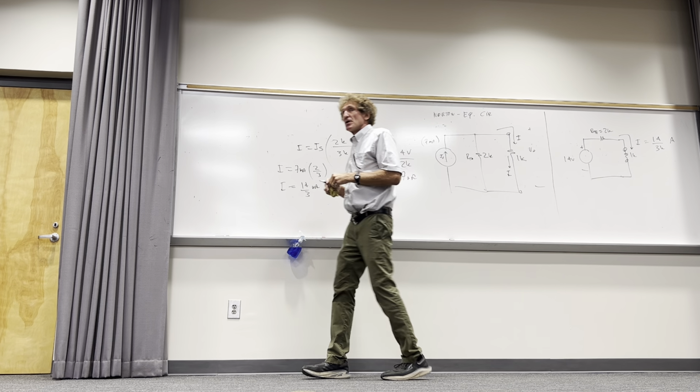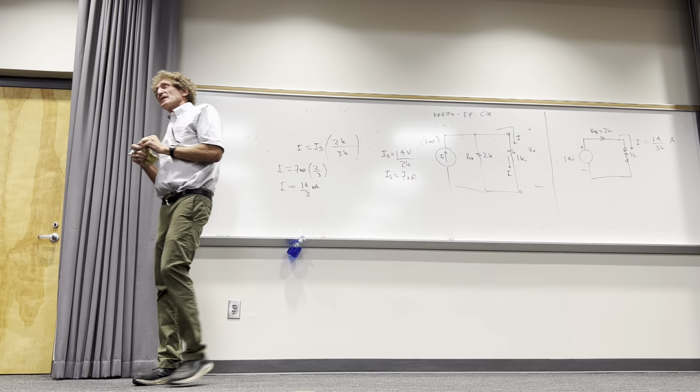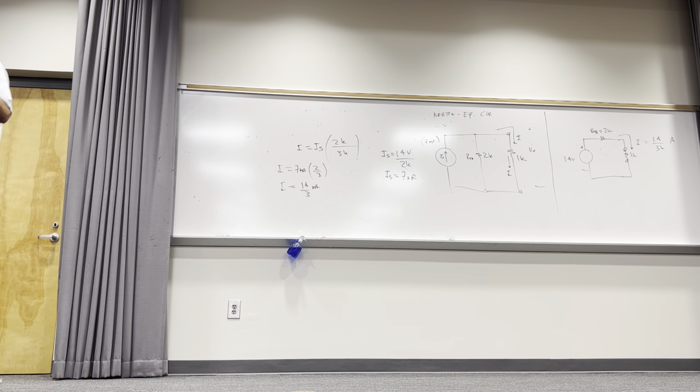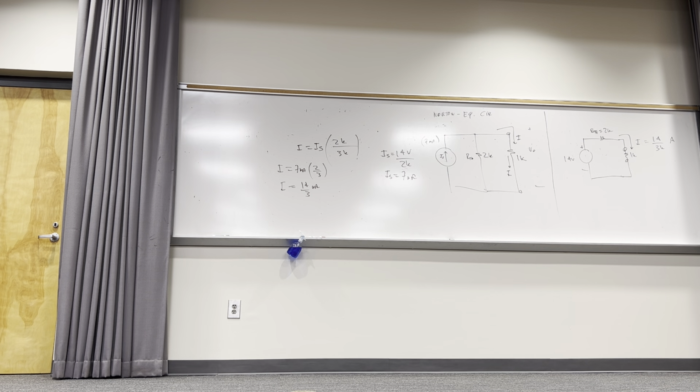It means instead of getting the open circuit voltage like we've been doing, you can get what's called a short circuit current. Just take the load off and put a wire between the two terminals where the load was, and find out what the short circuit current is, and then you can take that and simply calculate the rest of the problem. You all with me, class? Short circuit current is what I'm showing you right here.